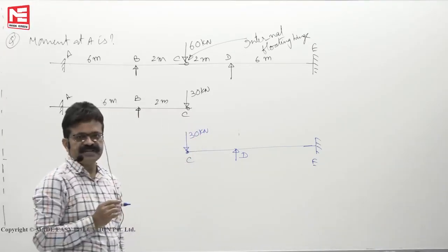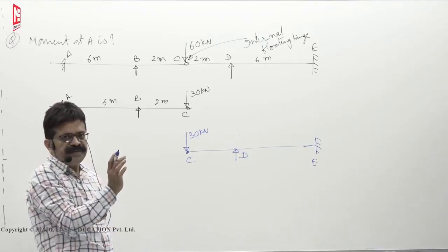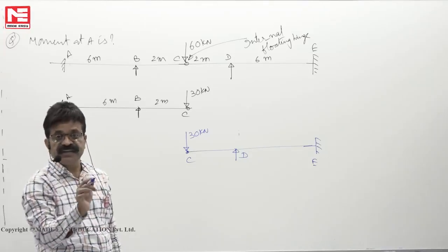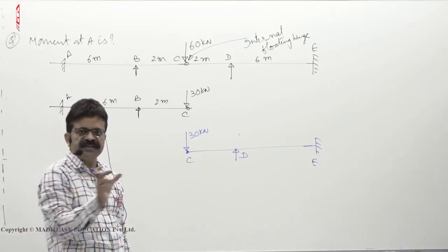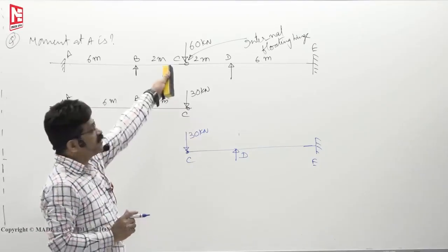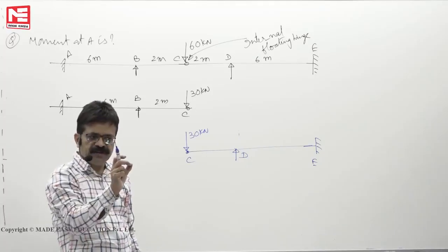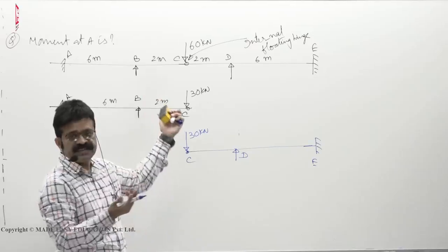In strength of materials, sir might have told you about hinge reactions. If on one beam the hinge reaction is downward, on the other beam the hinge reaction is upward. But they are hinge reactions, the reaction exerted by one member on the other member. But here it is not a reaction, it is an applied load. Then your applied load will be shared by the two beams in the ratio of their stiffnesses.